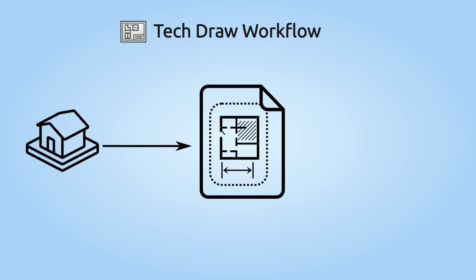These tools are completely different from the Draft tools because they are using different libraries. After that, the sheets are ready to be printed or exported to PDF. Most of the work using this workflow is done on the page using TechDraw workbench tools.